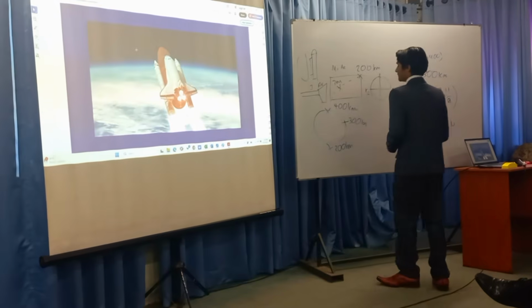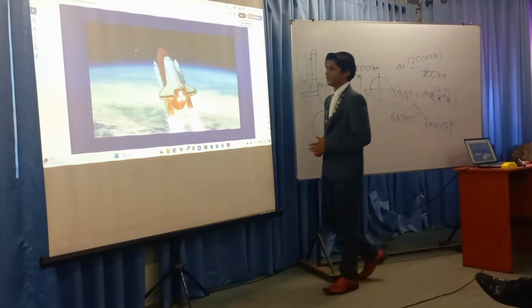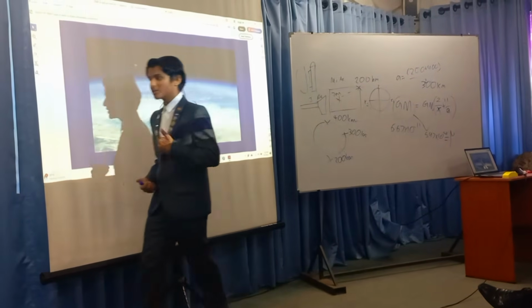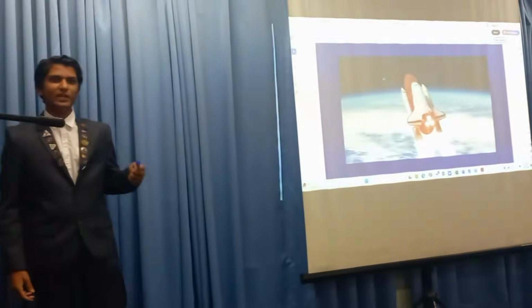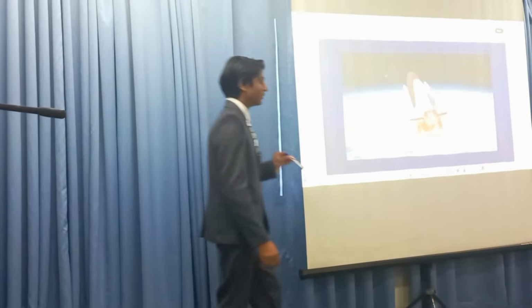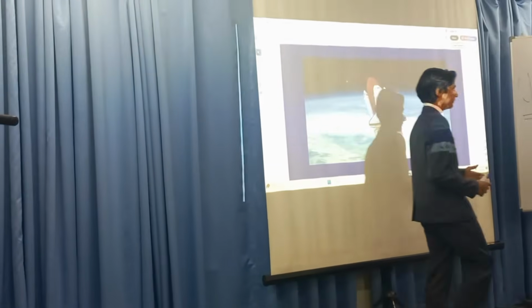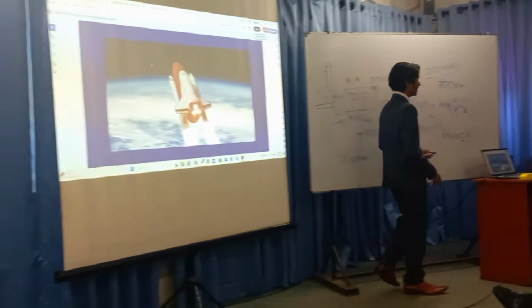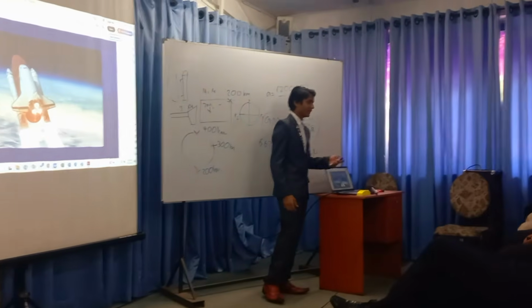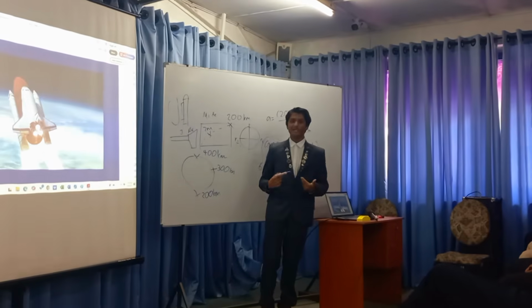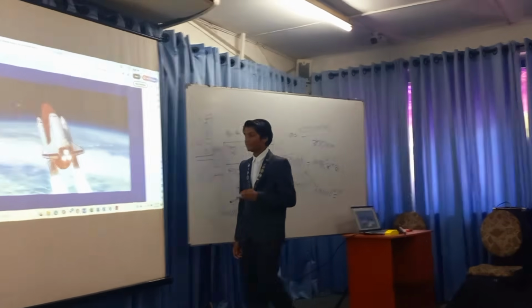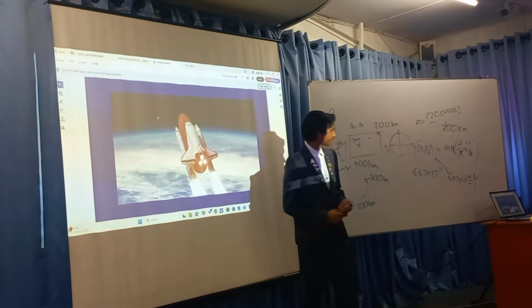We would gimbal the engines, and then we would reach something known as the main engine cutoff. The main engine cutoff stage is the point of the flight where the engine is completely cut off, and the fuel left is about 5 to 10%. We don't cut off the engines at, say, when the fuel is completely depleted, because that can damage the engine. Even in a standard aircraft with jet engines, if you let the fuel starve it, then the engine will be permanently damaged. And because the space shuttle must be reused, it's typically about 10%.